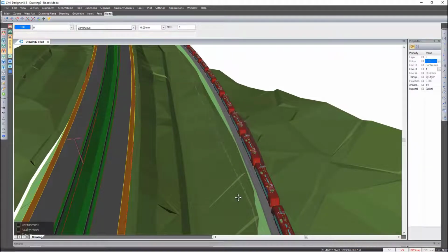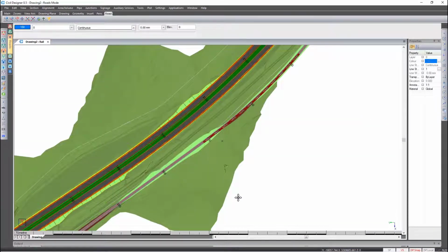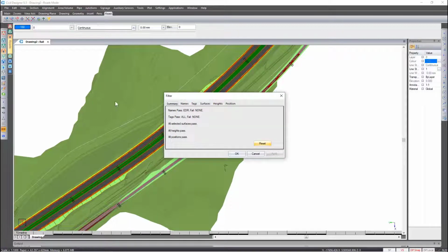The last functionality I want to show you is how you could go about utilizing the draft expert in order to create auxiliary services. So this would essentially be pipes that I'm going to show you next. Before I do so, I'm going to work with my name filter, and I only want to work with codes starting with CULV, and then put in an asterisk for wildcard characters.